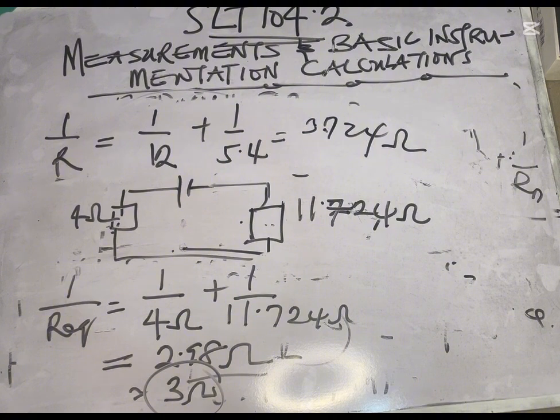When we resolved and we had 2.4 or 2.399 ohms, of course we went forward to resolve that 8. Remember, the 5.4 and 12 were separated by 8. We needed to remove that barricade, so we solved 5.4. You remember how we got 5.4? We solved for 6 and 4 that were in parallel, and then we did it with 3 that was in series, and it gave us 5.4.